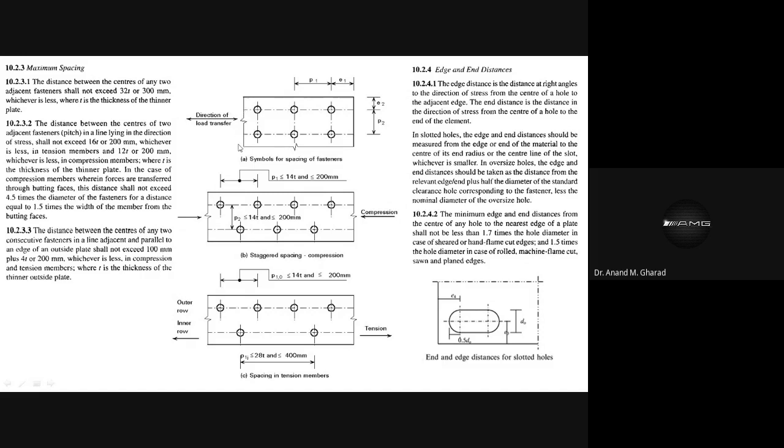Just try to understand: if this is a connection, these are the bolts which are placed. If one end is, let's say, fixed and the force is applied in this direction, the stresses will be developed in the same direction. If I apply force in this direction, naturally the stresses which are developed will be again in this direction, correct?